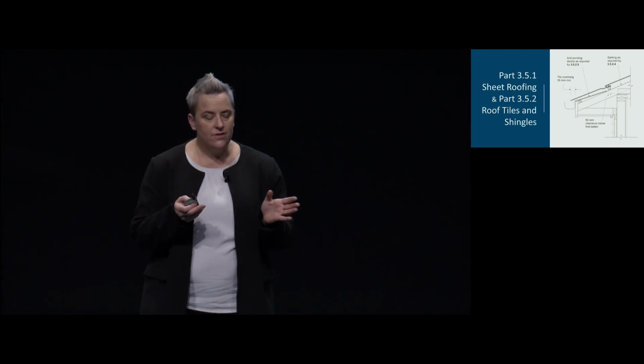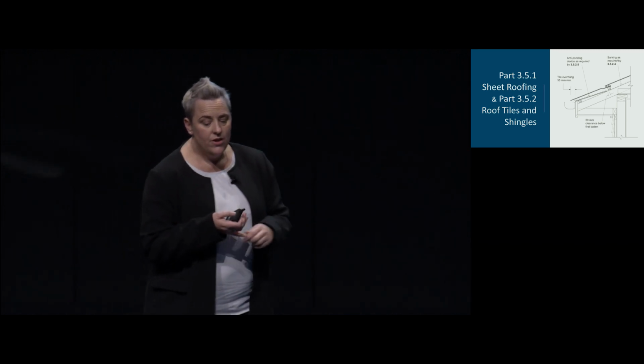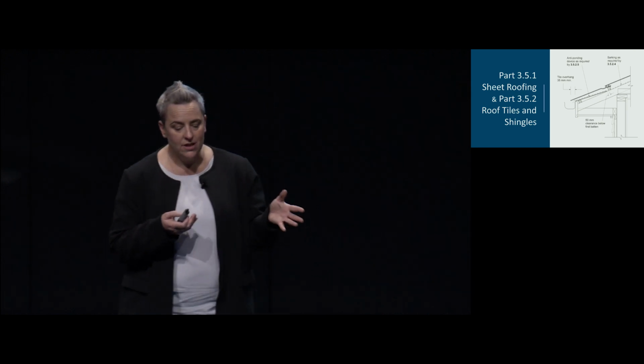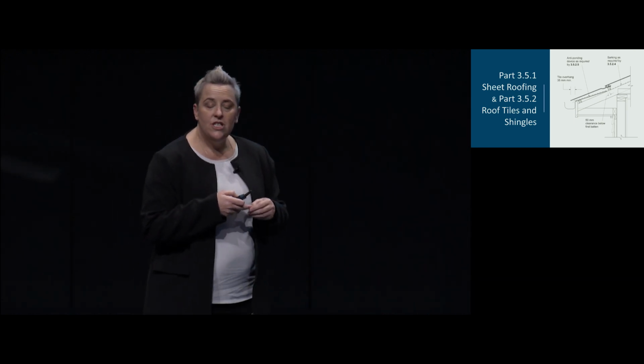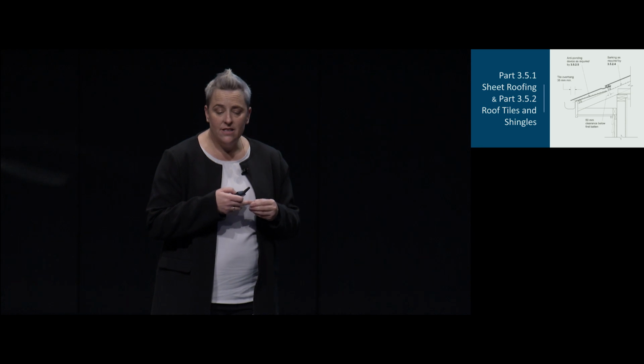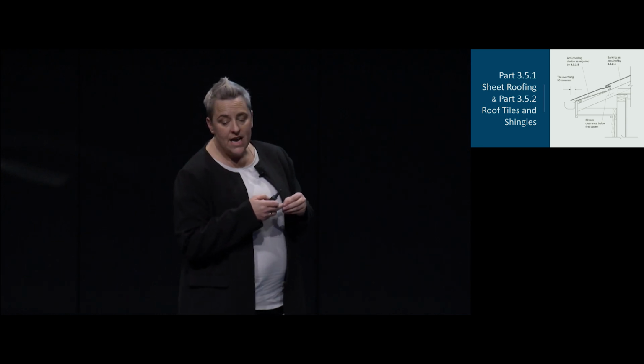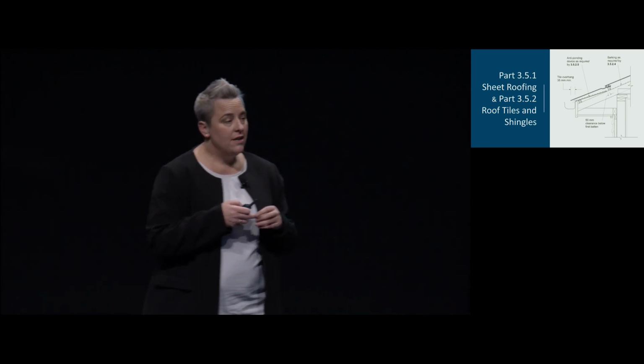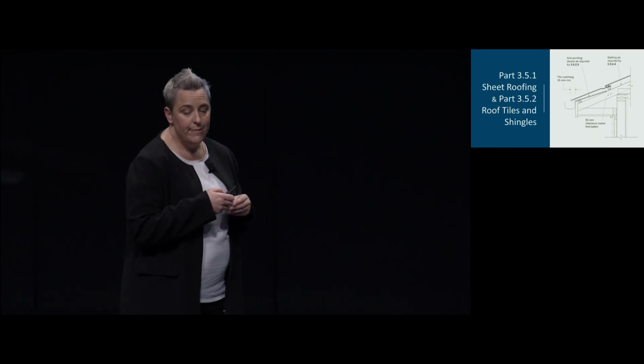So there is some guidance for the acceptable requirements, including the flashing abutting the masonry walls and the framed clad walls. There are some new discharge requirements for eaves and gutters for tiled roofs, and it now specifies that tiles must overhang the fascia or the tiling batten by not less than 35 mil, which is shown on the screen.